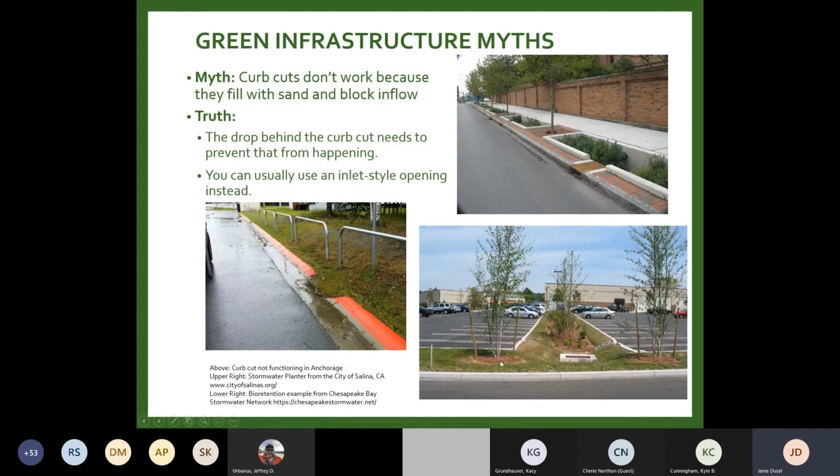Very much so. Same thing for here. This is more of a swale concept like this one, but look at the fall between where water's going to come into this facility versus where sediment is really going to accumulate. It helps a lot to give some vertical distance there. The other thing you can do sometimes, maybe they couldn't make this any deeper. Maybe there's a utility line here or some other vertical constraint, so you couldn't actually give this vertical separation.